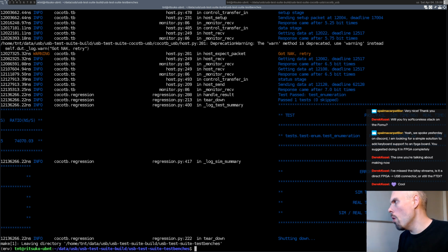The FOMU you always get to the bootloader first, because since it doesn't have an easy way to reboot it or a button or stuff like that, the safest way is to always go to the bootloader step. For this board, if there is an application loaded, it will skip the bootloader. But I want the application to have an option to reboot in DFU mode, with always the fallback that if you have the user button pressed once you plug it in, it goes to the bootloader by default.